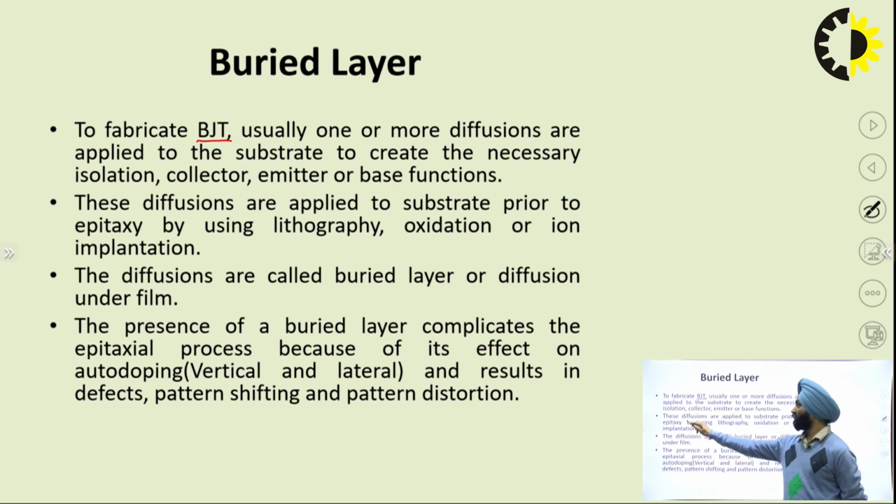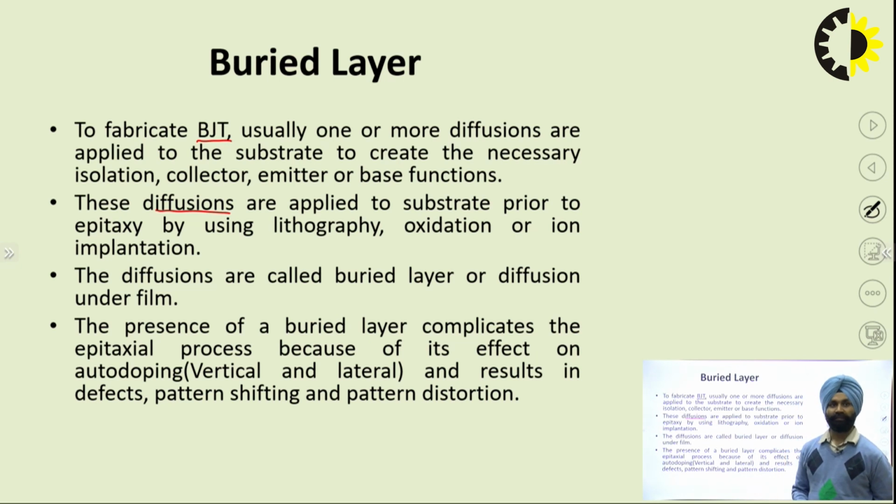These diffusions, when applied to the substrate, may create the diffusion under the film. Those are called the buried layers. These diffusions are generally done before the oxidation and the ion implantation that we have discussed in the main lecture series.